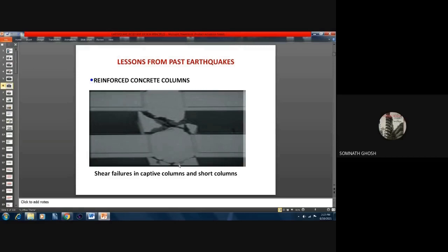So that's why sometimes there is a tendency of engineers just to make some walls at the ground floor level or just provide a tie beam in between. And they think that if they can break the column length, make it shorter, they are making good for the structure. No. If they do like that, the stiffness of column will increase, 12EI by L cube, in cubical terms. So you just think.